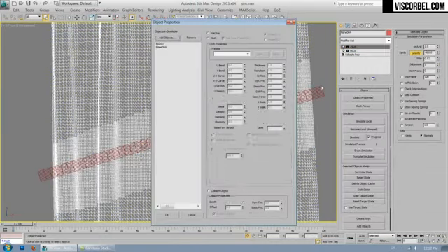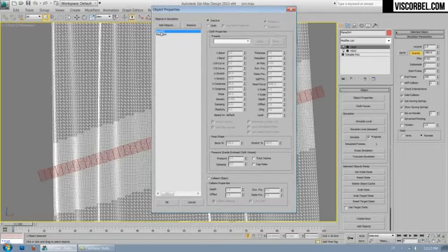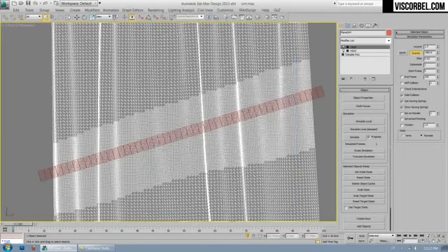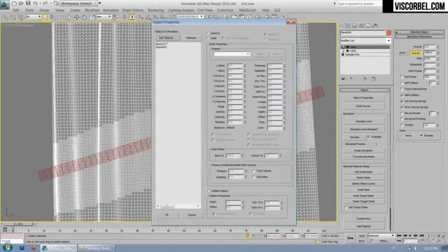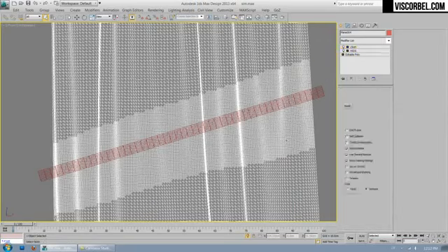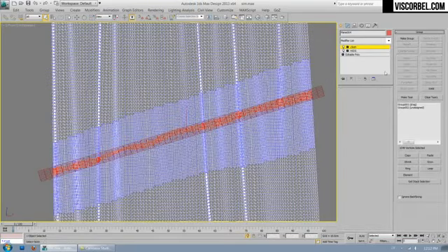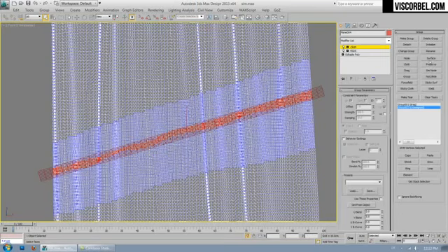Actually, it looks like there's some sort of a glitch sometimes when you add a collision object and you set it to collision object, it doesn't confirm it when you click the OK. So you have to go in again and double check if it's set to collision object. So this can cause some side effects, like you want to assign the group to a surface but you can't click on it because it's not set to collision object. So double check that if you get this problem. Right, once we fix that, we can attach it to the surface.